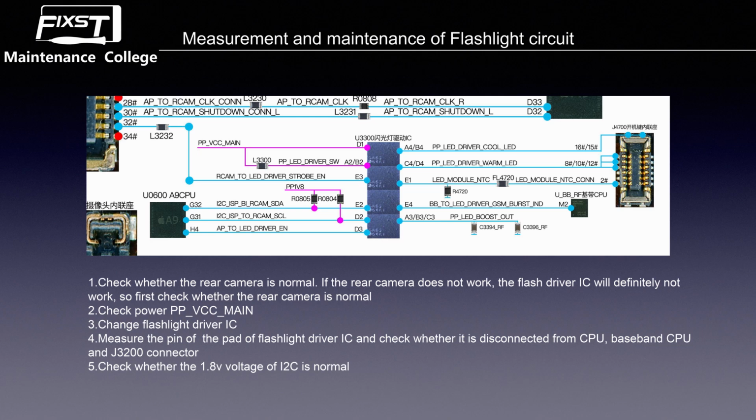So we mainly test these two resistors. If these two resistors have some problem, the boost system for the I2C, this power, will also be abnormal. So we need to test these resistors. Because these two resistors are pull-up resistors, if they have some problem, we just need to change them for the same resistor. We cannot make a jumper, and we cannot use another type. You need to use the same type.